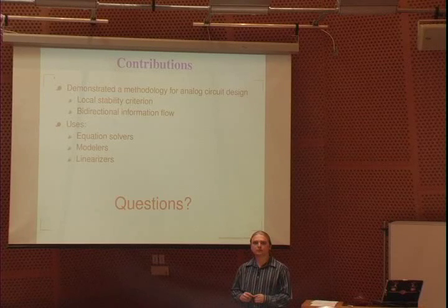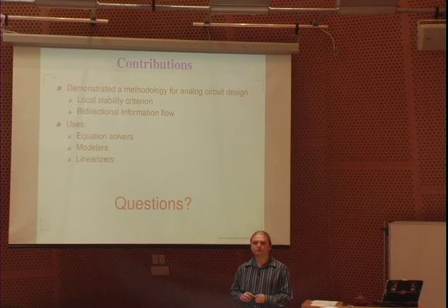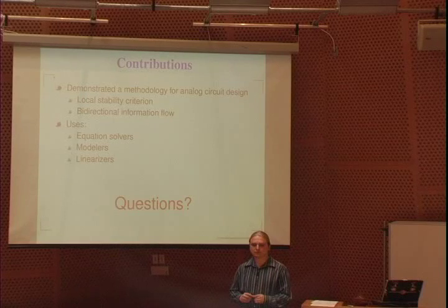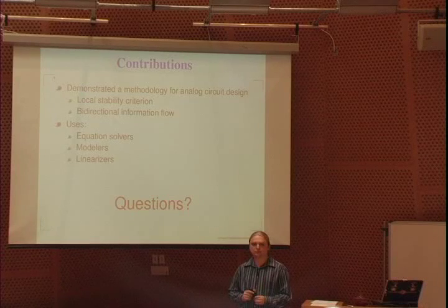For example, if everything was linear, just dominant pulling every local node would suffice. But if it's nonlinear, it's not obvious how you do scaling. If the intentional capacitances were sufficiently larger than the sum of all the internal parasitics, or the root gain of the linearized group, are you guaranteed convergence because you have enough phase margin? Do you have any theorems?